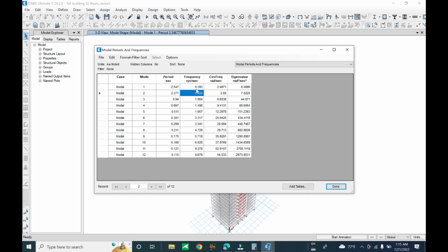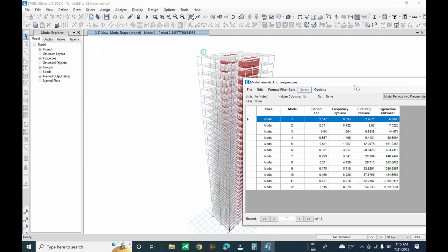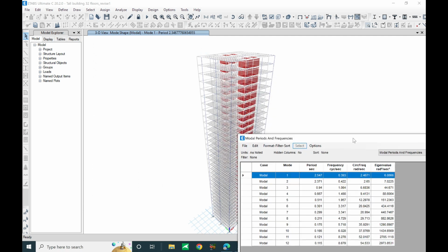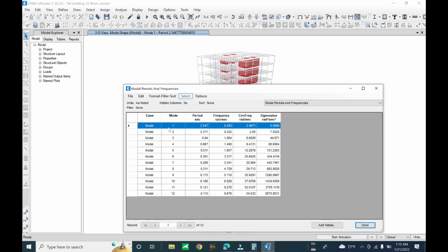We have to increase the value to at least 1. So for model 3 it is acceptable, but we have to add more walls and more thickness to our frame to increase the natural frequency.